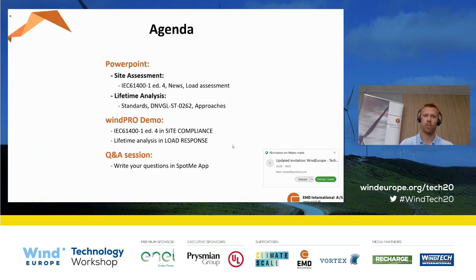The agenda I'm going to take you through today is first a bit of PowerPoint. We will look into site assessment, in particular the -1 Edition 4 standard, what is new and how it relates to load assessment. Then I'm going to shift to a lifetime analysis, look at the different standards, and in particular zoom in on the DNV GL standard and the possible calculation approaches in that standard. Then we're going to make a shift, hopefully without any issues, to a brief windPRO demo of how to do the assessments in site compliance and load response. And in the end, there'll be time for some questions.